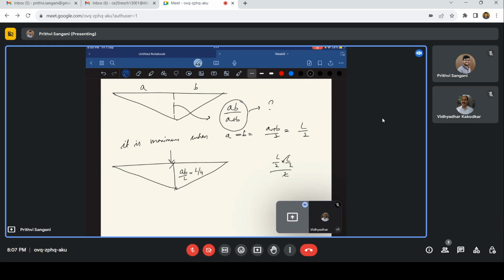So in this case, what do we need to do is, again, like we said, we know that the maximum bending moment happens in the midspan. So you place your UDL. In our case, it is 2 meters. You place the UDL in such a way that the maximum point, the point C, divides the UDL into half. Okay, so you'll place half here and you'll place half here. So that itself gives you the maximum bending moment. So if you find the area here, you'll get the absolute maximum bending moment.